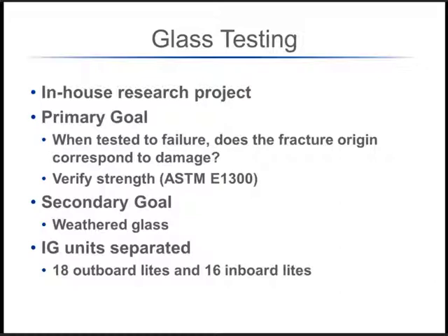And also, based on the opinions of the opposing consultant on the project, we wanted to at least verify the current strength of it. And did it meet ASTM E1300? E1300 is the design standard for load resistance for glass. So if you're trying to determine a thickness or type of glass to use in a building, ASTM E1300 is